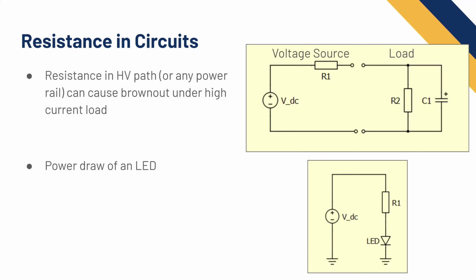If you want to learn about RC modeling of a battery, I can talk about that at the end of this, but that basically creates some parts that are time dependent, but at the simplest, just a resistor, right? And as we just learned, current times resistance equals a voltage drop. So let's say that our battery is 600 volts, right? And let's say we got the resistance in our battery all the way down to only 1 ohm.